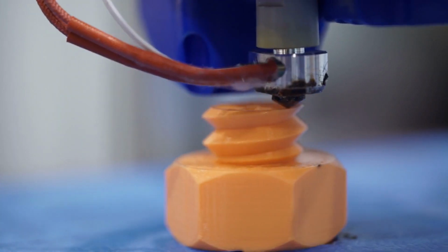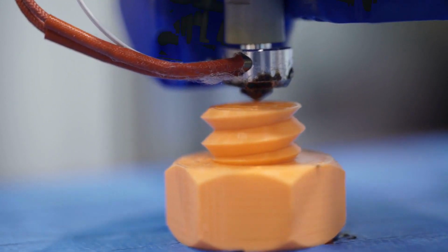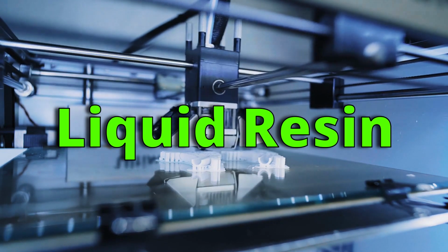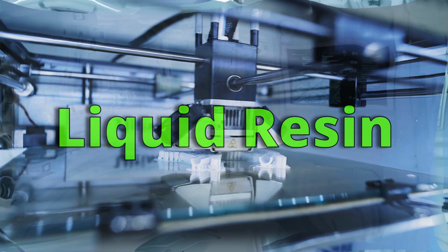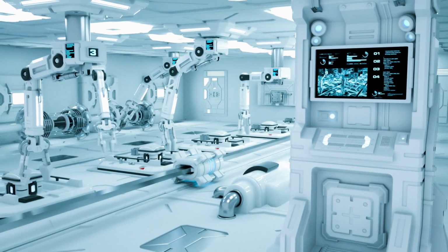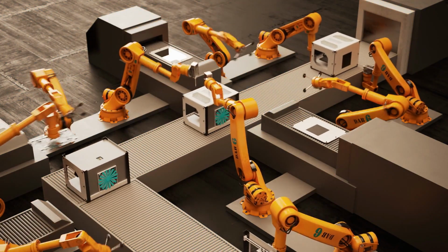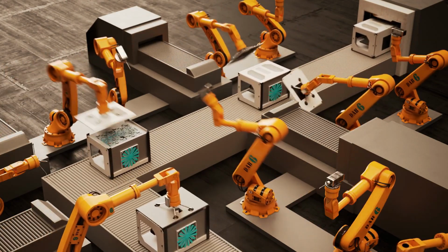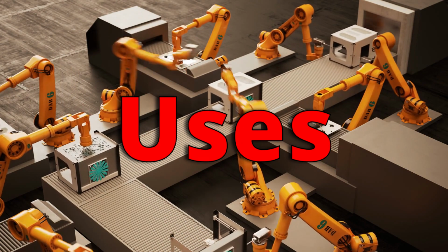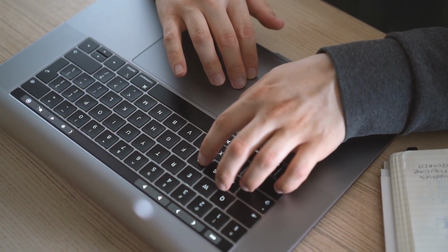FDM uses plastic filament, which it melts, and using an extruder it steers it on the build platform, where it eventually solidifies. SLA uses liquid resin and a laser that will solidify or harden the resin. SLS uses powder, with a laser unit directing a laser to a reflective mirror, and using a motor to steer it and point out different areas on the build platform. And DLP, similar to SLA, uses liquid resin, but instead of a laser, it uses light to harden the resin all at once. And this is it on 3D printing and how it works.